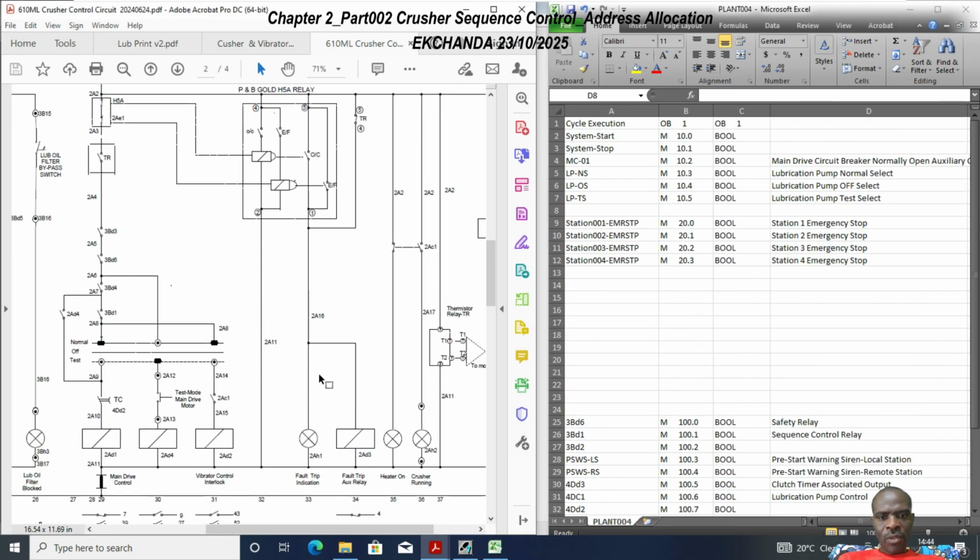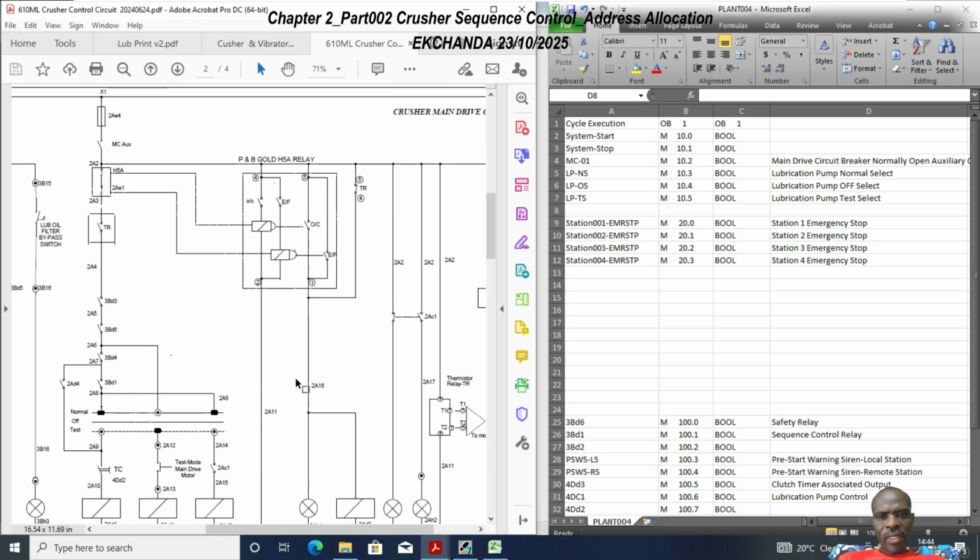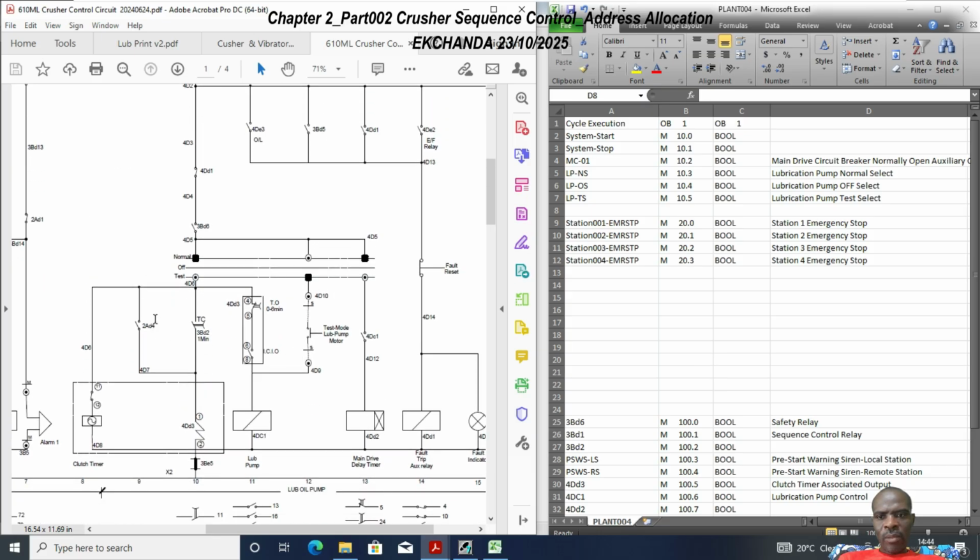Okay, so within this schematic, we've got 284, which we've already looked at. In case you've forgotten, 284 is here. It's an output coil. In actual fact, it's the coil for the main drive. Is it? Let's see, 284. So test relay. For the test mode, you energize 284. So it's basically a control relay. So we're not going to worry about 284.